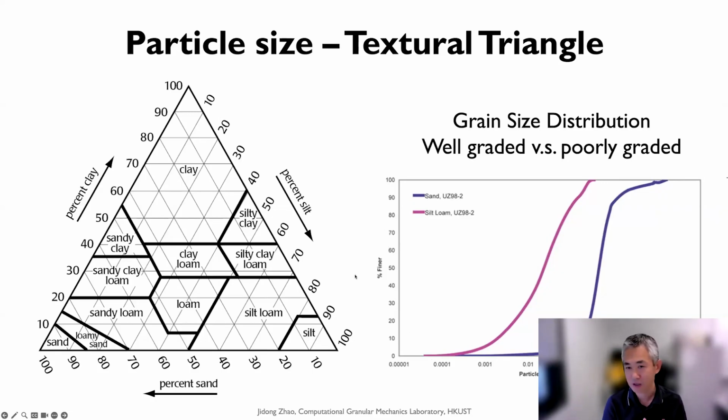Basically, the vertical axis is the cumulative fine content, and the horizontal axis is the particle size or particle diameter here. The left and right basically give you different average sizes. The left is definitely the finer average size, for example, it indicates a silt range, and silt is in this range here, right?